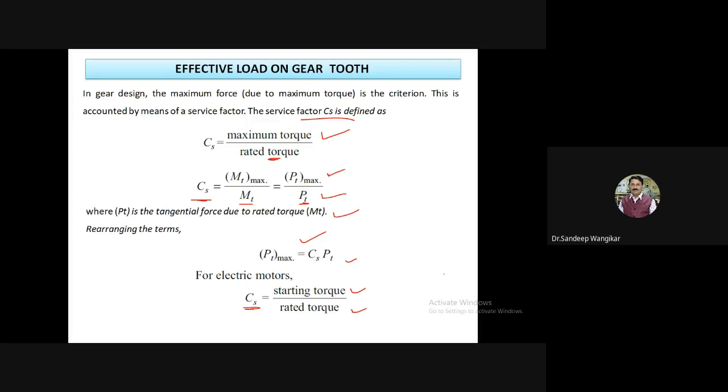Then what are you doing? You are driving your bike on first or second gear. You are not using your bike gear as third or fourth. Just imagine why. Because at that time, RPM is not the criteria. Your bike requires more torque, more power to drive along that inclination. And if you are on a smooth, plain road, then what is your criteria? You can go for fourth gear, or if there is a fifth gear, you can go for that, because at that time torque is not the criteria. You can proceed with the normal average torque, the rated torque.